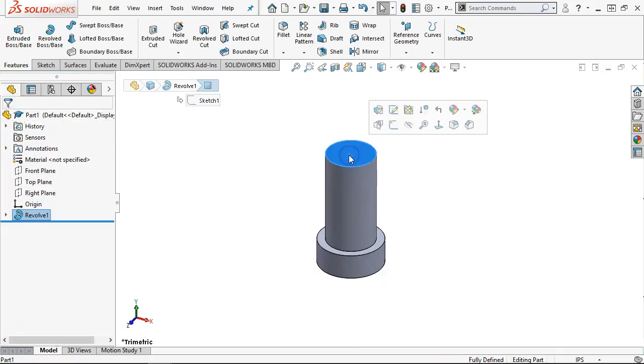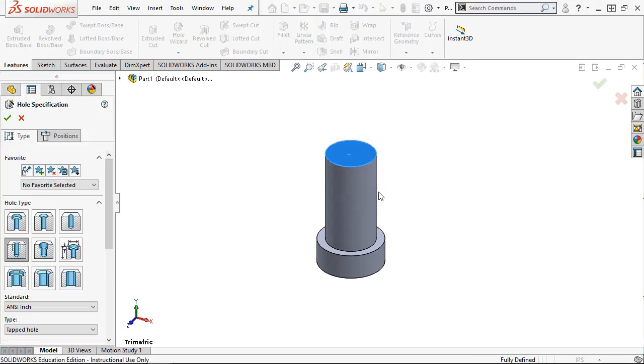Right, and then I'm going to create a hole wizard. So I didn't grab a button head or a socketed cap screw. Couldn't think of it. So we'll have to, as we go further in and we do our positional tonight, we'll have to build those. Make sure that I have something that actually has some clamping. Or if I need to, I include the length of the screw to have a washer and have it retain.